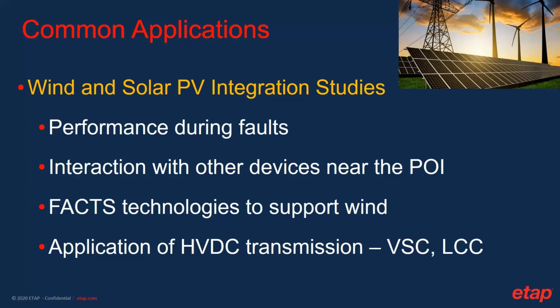When you have two or more power electronic based devices, for example, two wind farms in a local area or a wind farm and a STATCOM FACTS device, people have found over the last few years that these devices can interact in a negative, unstable manner, and lead to what we call control interactions. So again, EMT simulations are commonly performed to identify any control interaction related issues.